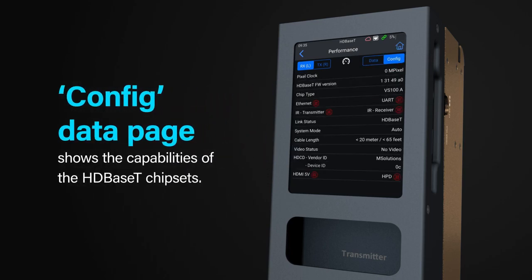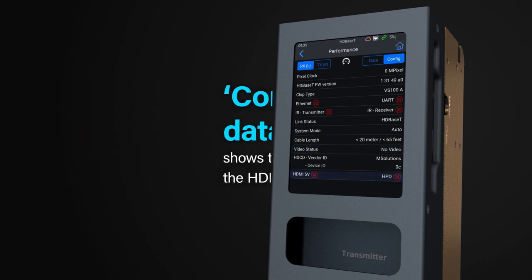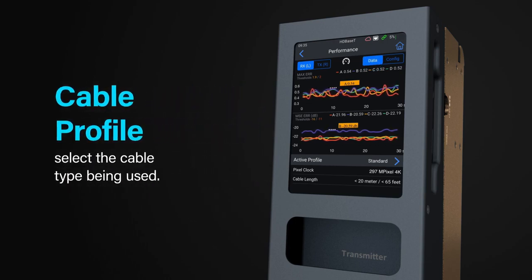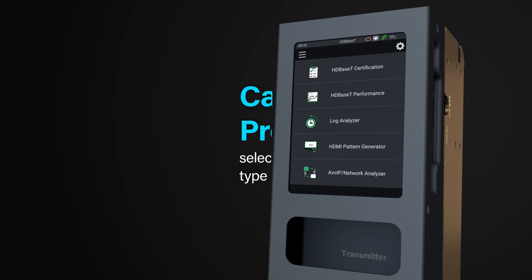The config page allows you to drill down into the individual features within the HDBaseT link, such as pixel clock speed, Ethernet pass-through, UART or serial pass-through, bidirectional IR pass-through, video status or the presence of a video signal, and 5V hot plug detect. When testing with a specific CAT cable type, use the cable profile to select the cable being tested. This function will allow for properties of specific cable to be taken into account when testing. If your cable type is not listed, leave it selected as standard.